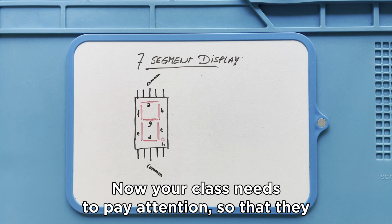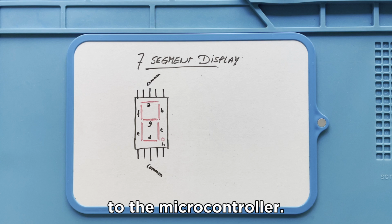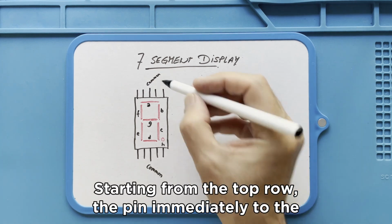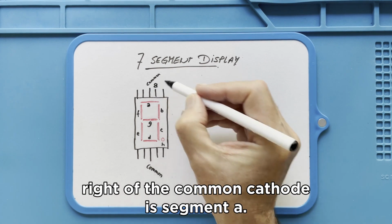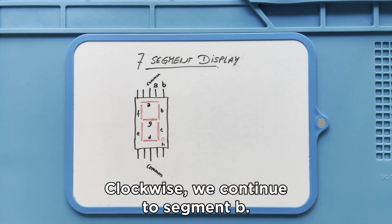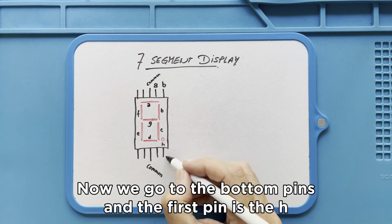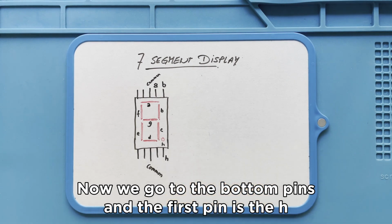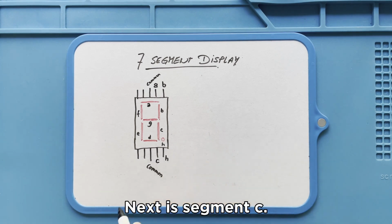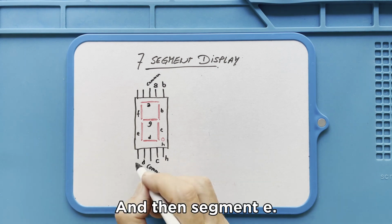Now your class needs to pay attention so that they will not make any mistakes when connecting the display to the microcontroller. Starting from the top row, the pin immediately to the right of the common cathode is segment A. Clockwise, we continue to segment B. Now we go to the bottom pins, and the first pin is the H or decimal point. Next is segment C, then segment D, and then segment E.